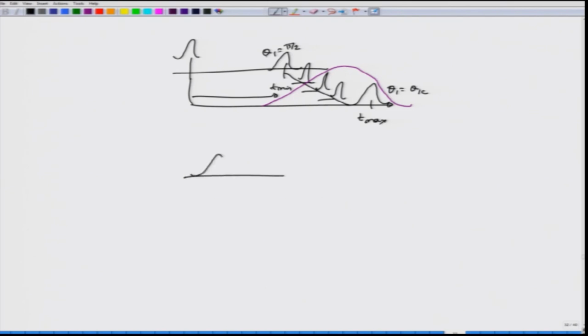and if I had only a single mode of propagation, then I could just transmit right after this arrives at the receiver, at T min, I could transmit another pulse. Okay, so, maybe another pulse follows here. So, this pulse would arrive at the same time T min. So, it would be possible for me to send multiple pulses at a much faster rate, because the pulses are not getting broadened. Okay, we are ignoring other types here, but the pulses are not getting broadened, but because of this broadening nature, I have to wait for quite a bit of time.